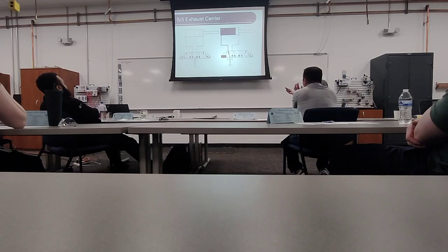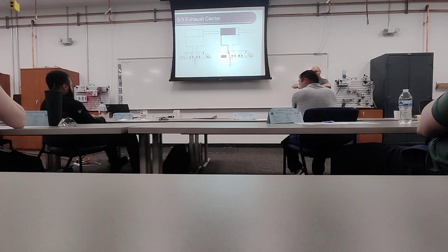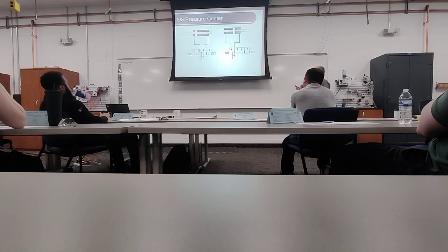When you want to be able to move the actuator without turning the air off the machine. So if you had a clamp and you wanted the operator to blow, or it could be something as simple as a box erector where the two actuators fold down the tops of the box. And the box gets crunched. And they need to get it out. Well, they open the door and they can't move the actuators because it's a 5-2. So now you have to shut the air off the machine to do that. Well, if you had exhausted centers, you could move the arms out of the way, get the box out, reset the machine, and get it running again. So any place you can get into a jam, basically.